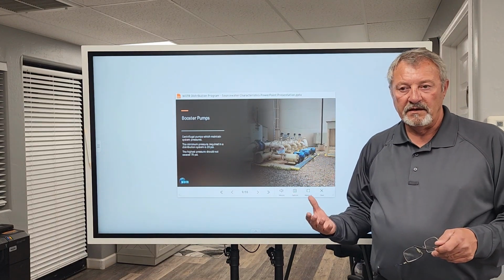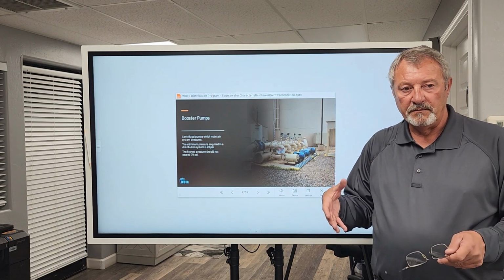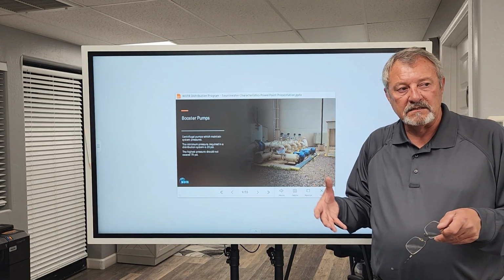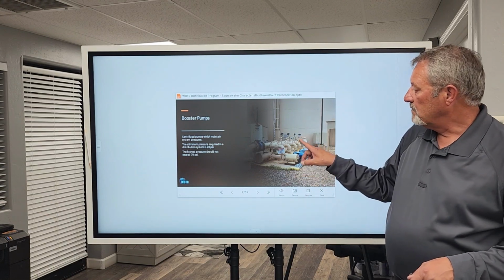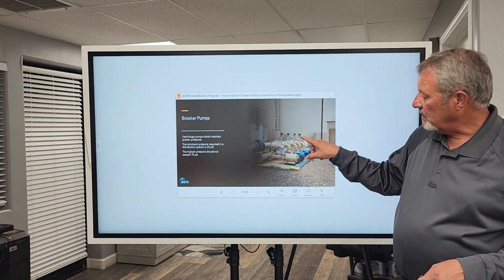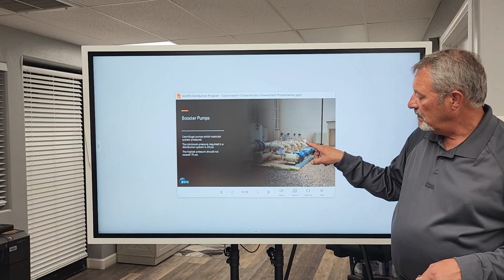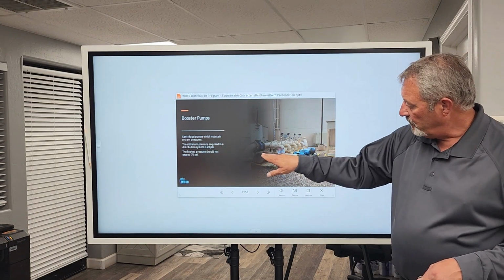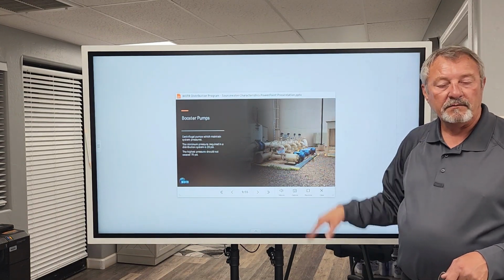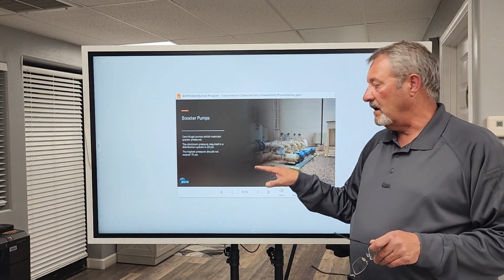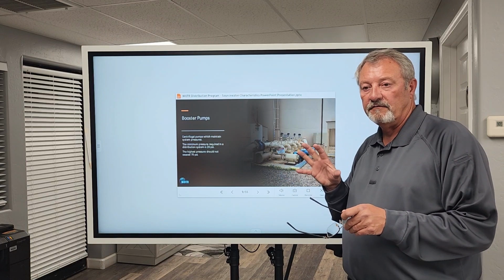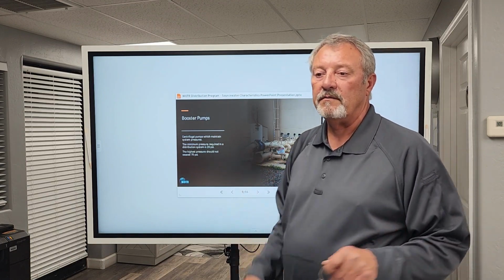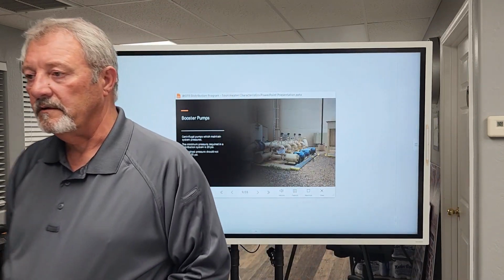Because of the type of pump it is, the volute, the pump itself where the impeller is, needs to stay primed, full of water. So to do that, we have a pipe that comes out of the ground storage tank and comes along and pushes water to every pump. It keeps, just by gravity alone, the volutes of all these pumps primed. So why is that important?